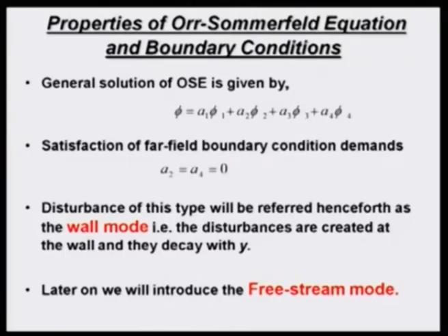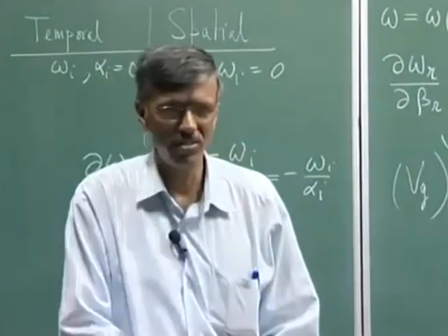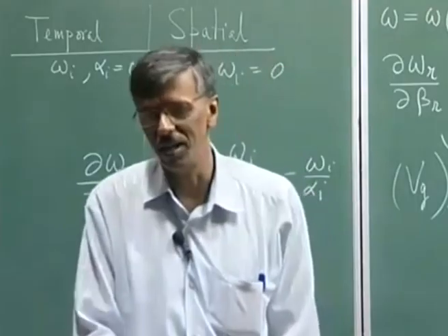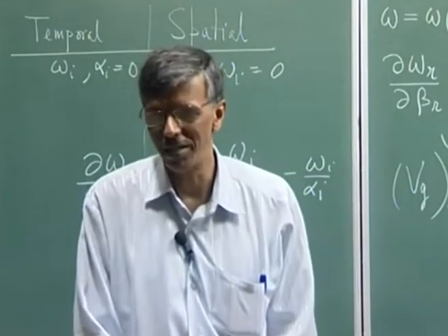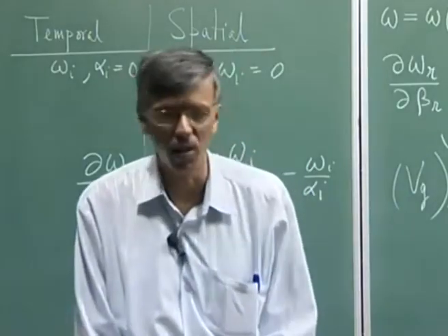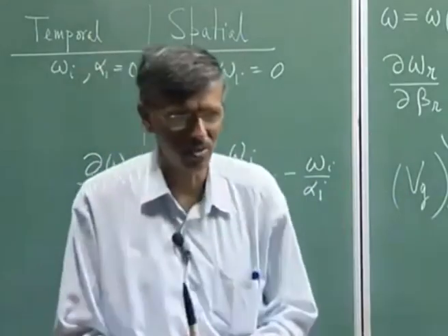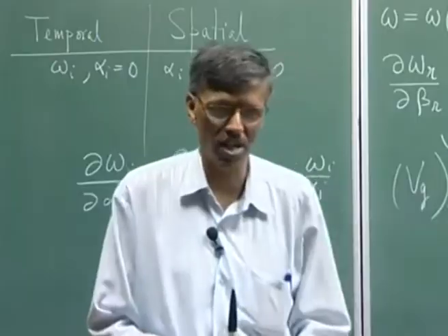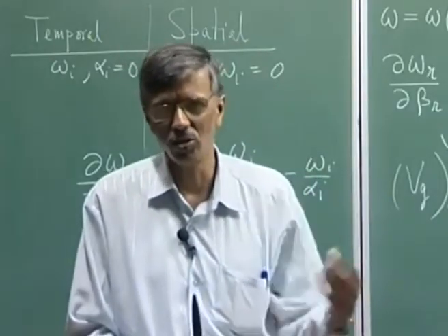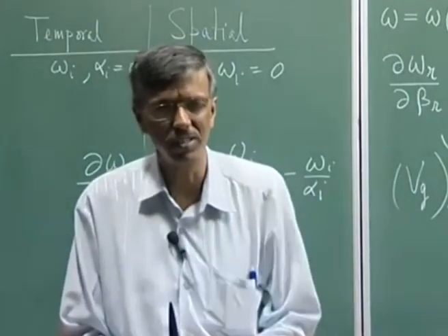A good example also comes from the engineering side, when you look at what happens inside a gas turbine. There you would see, be it in the turbine or in the compressor. Talk about the compressor, it is a cleaner flow, but you have the stacks of rotor and stator, rotor and stator. Okay. So, from the stator what do you get? You get vortices, right. Those vortices go downstream, because that is the mean convection direction.